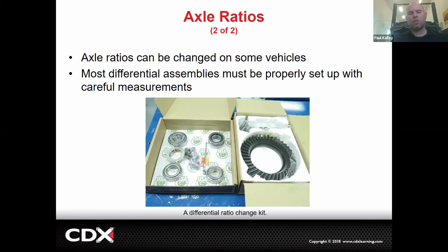And if you wanted to do a regear, you can. If it's rear wheel drive, this is all you need right here. It comes with the ring gear and the pinion. Those, by the way, are married. I've explained this before. When they make the gear, they make the ring gear and the pinion, and then they put them on a machine with some lapping compound and they literally run them together. That's a set right there. You don't change a ring gear and not change a pinion. By the time you change a ring gear and leave the pinion, that pinion has already worn in.